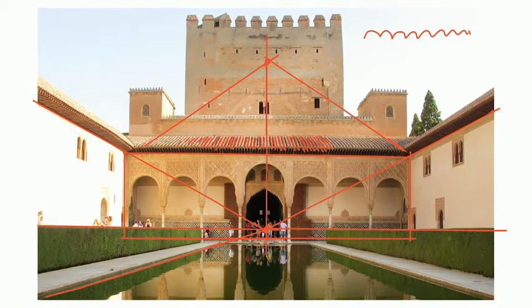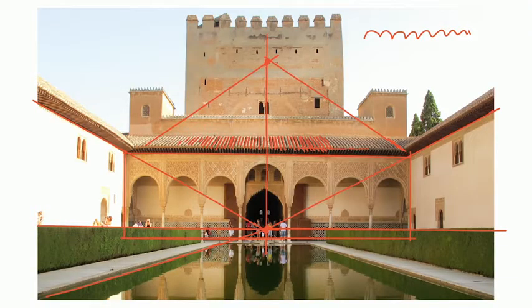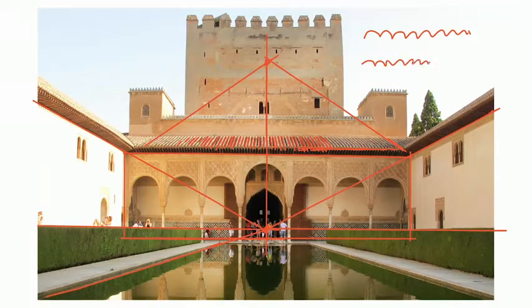The other thing I wanted to mention is the thickness of the material at the edge of this roof, which is right in here. So in drawing tile roofs, that edge is really important. You wouldn't want to show that as a straight, heavy, flat line. Again, let's use an expressive line. So it might be something quick like this, or you could just do something like this. It's just kind of an impression of what those tiles are doing at the edge. But they have a thickness, and it's important along this edge to read the texture of the tiles.